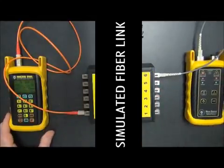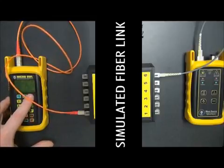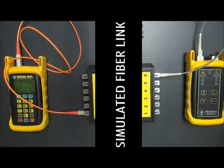And finally, we store a reading for fiber number 6. Okay, now as you can see, all of those readings passed, so we have a good link. All the fibers are good, they all pass. So once we're done testing all of these fibers, we're satisfied with the results. We can take the micro owl to a PC and download the test results into a certification report.